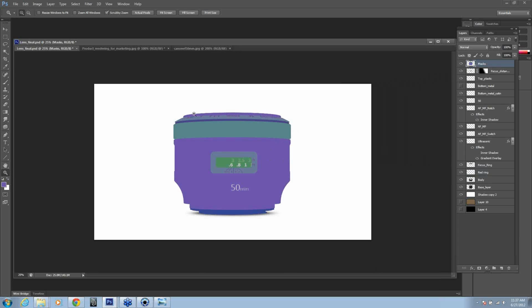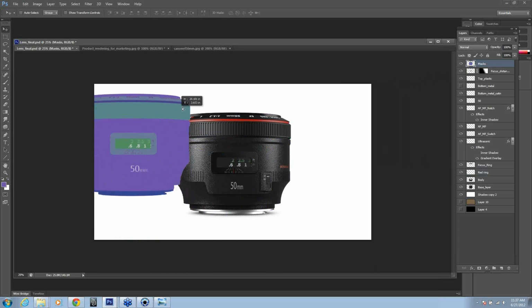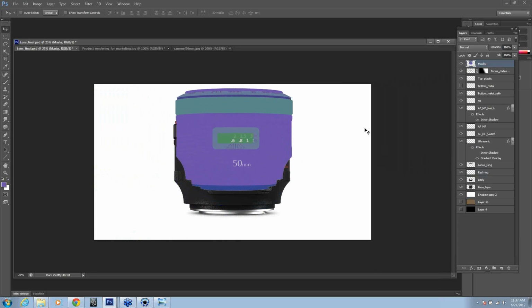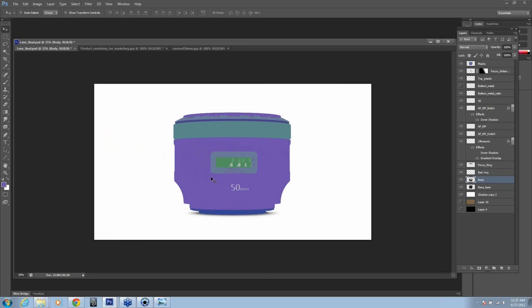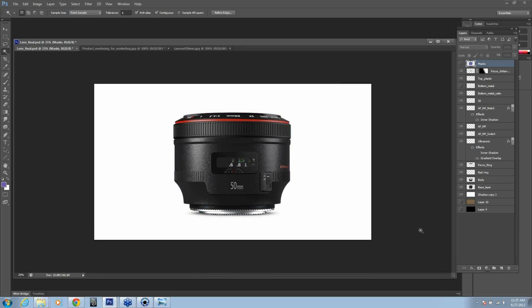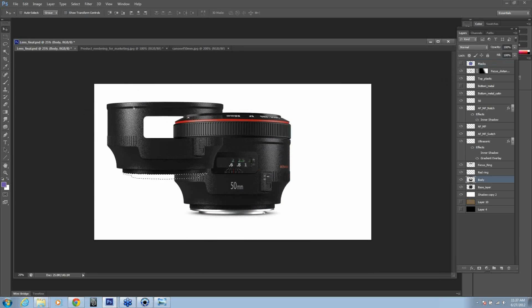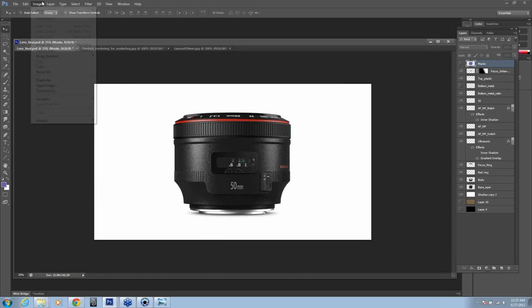Now, what we're going to set up next in KeyShot is basically this masks file. What this does is create flat shaders that you can use in Photoshop. Select your magic wand tool, and you can make precise selections of certain areas of your render. The reason you want to do that is that if you need to control a certain element of your image, you can do so independently by selecting it.